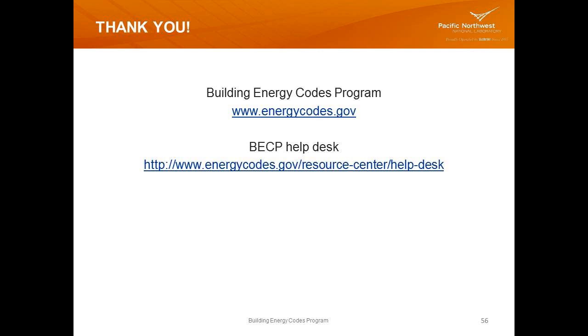Yeah, this is a good question. It comes up somewhat frequently, but depending on the code, and to be more specific, the IECC codes will strictly enforce that you can't go above the fenestration requirement of 40% or 30%, depending on which code you're on. If you want to get a bump of 10%, you have to agree to do advanced daylighting control features in your building.